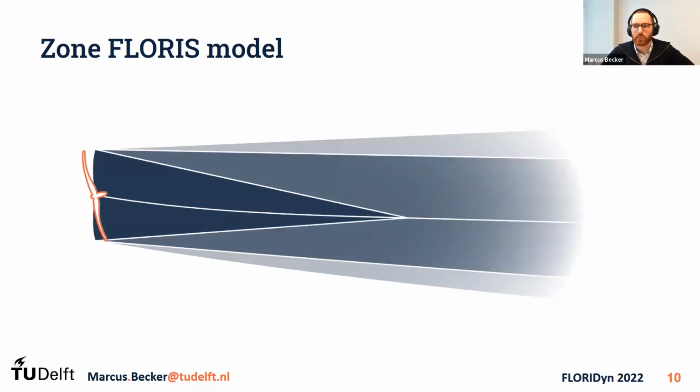If we now misalign the turbine, the model tells us how the wake will behave based on that. And the key takeaway here is that all we need to do in order to calculate this wake is we need the downwind distance, then we get the deflection based on our turbine state, so yaw angle in this case, and the actual induction. And then we can calculate our deflection. And from there, we can also calculate the boundaries of the zones.